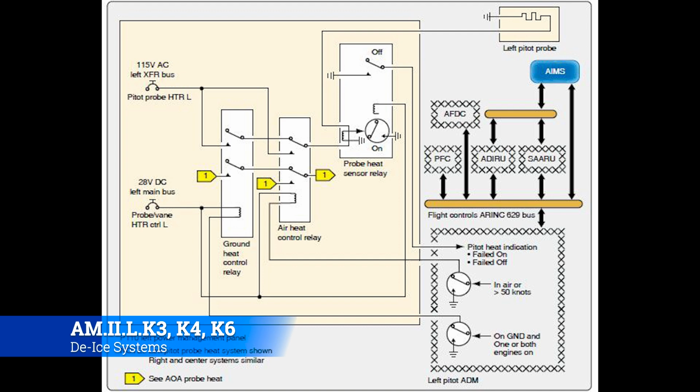It's going to pipe a certain electrical value into the pitot tube, and then ground it out. Then the pitot tube becomes basically a big resistor, or has a resistor in it, and that generates electrical heat. It does it very effectively, gets very hot and keeps it going. You're going to see this same sort of architecture in pretty much any of the systems that are thermoelectrically heated to prevent ice from showing up there.